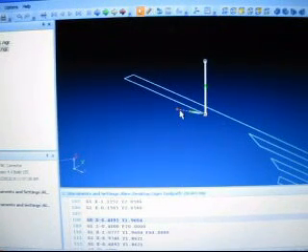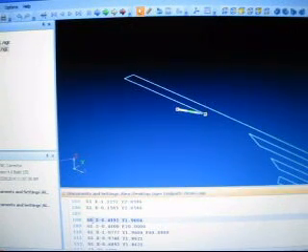I want it to go to this position, okay? But I don't want it to rapid there. See, that's a G0 command. We're cutting 0.4 of an inch deep, and I do not want it to rapid, because I'll probably have the thing set to 120 inches per minute for rapid. Okay, I don't want that, so I'm just going to backspace and change that from a G0 to a G1. Done.